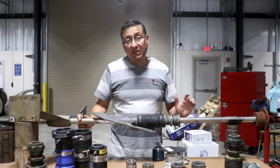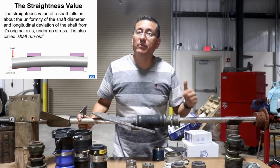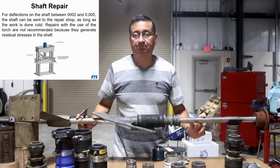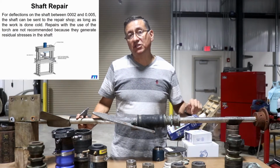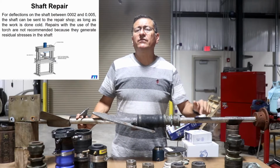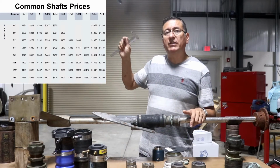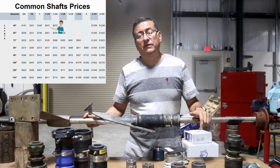This shaft is a special material. If this shaft is bent, I don't recommend trying to straighten the shaft in a hydraulic press. If this shaft is bent, I recommend replacing the shaft. The price of the shafts depends on the length and the diameter of the shaft. If you check, those shafts are not expensive.